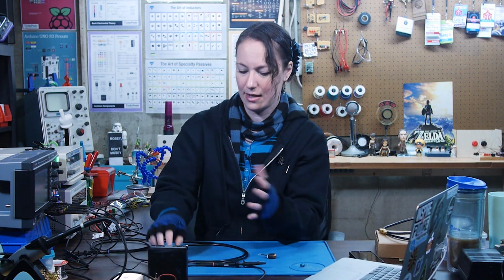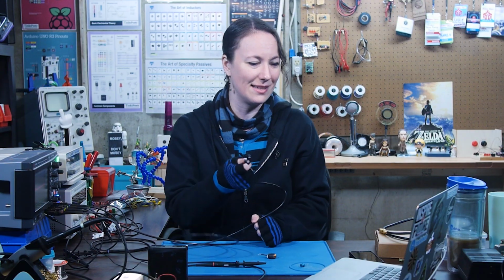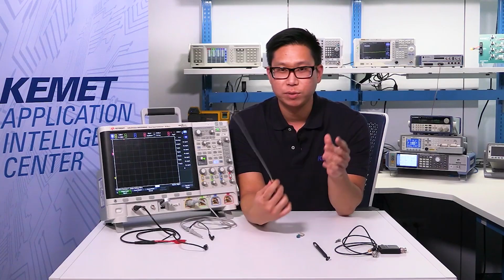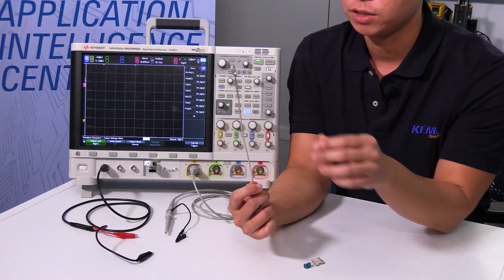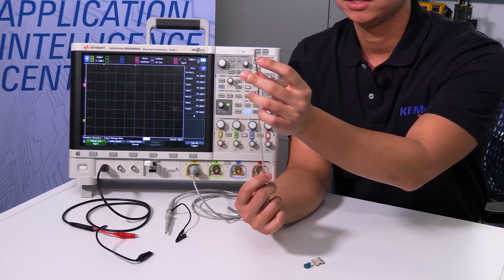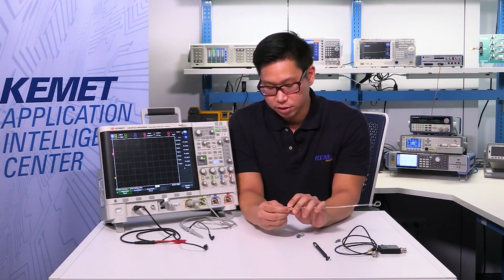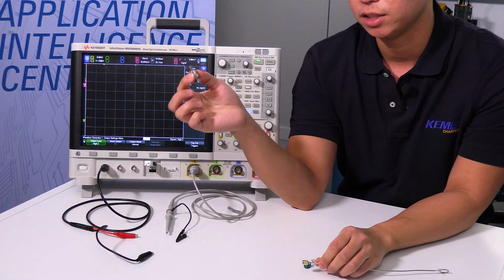So to do this test, I had to make this fancy probe here. Now, do you want to tell us about the professional probes versus this kind of janky looking thing that I made here? Yes, so typically these are called H-field probes, and usually you'll buy them like this, and they'll come with a cable and an amplifier. We are going to make our own, and you can make your own very easily by using a coaxial cable, a 50 ohm coaxial cable with preferably a single rigid center conductor, where you make a small loop on the end and you connect the center conductor and the shielding to the shielding of itself, and then you cut a little notch on the very top. And once you do that, you can hook this up directly to your oscilloscope. If you have an SMA connector, then you'll need an SMA to BNC connector and measure emitted electromagnetic fields. And so that's what we're going to look at today.